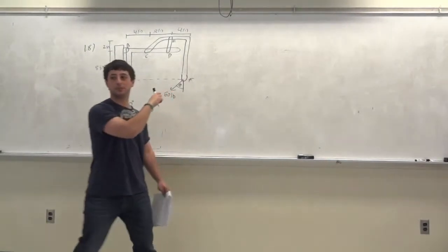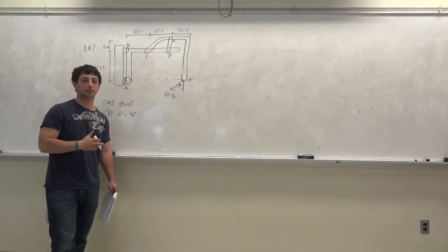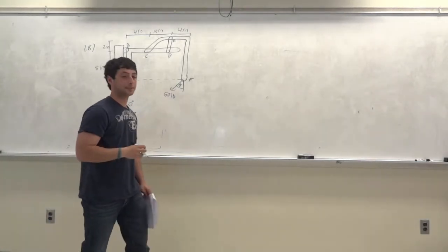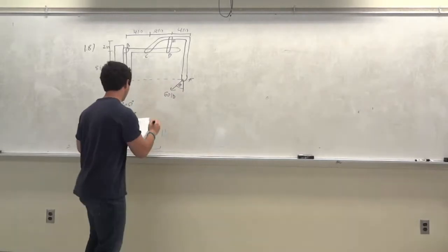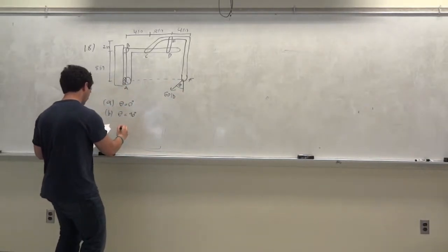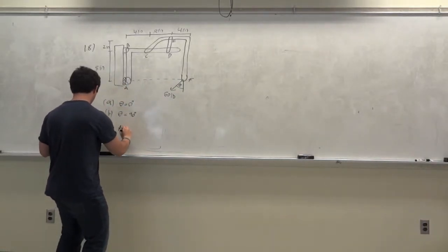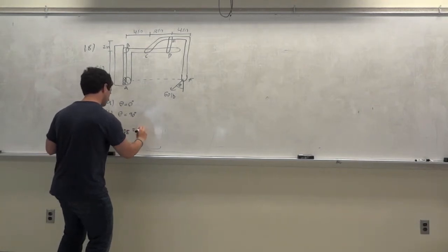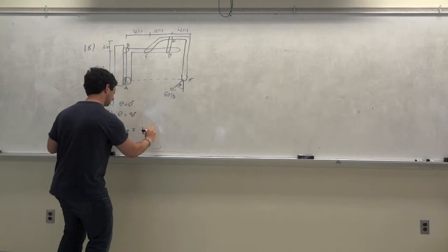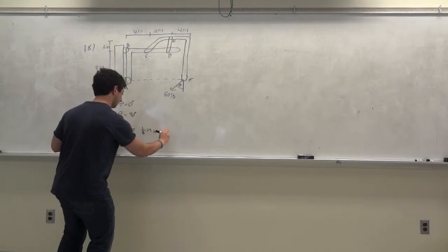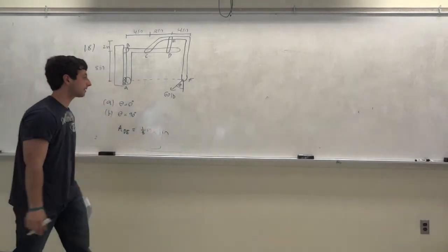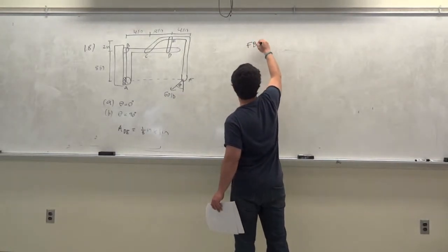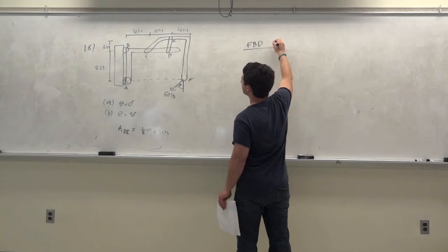Okay, so let's draw a free body diagram of this. Do you guys remember this from statics? It's just statics over. The only new concept is stress. Oh, and they give you the cross-sectional area. They say the area of link DE is 1/8 of an inch times 1 inch, so it's 1/8 of an inch squared. Okay, so let's draw a free body diagram of link CEF.